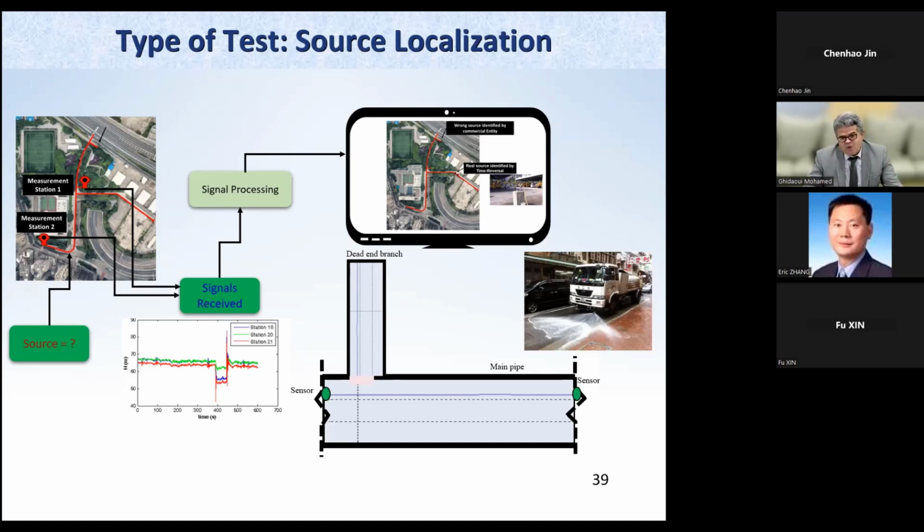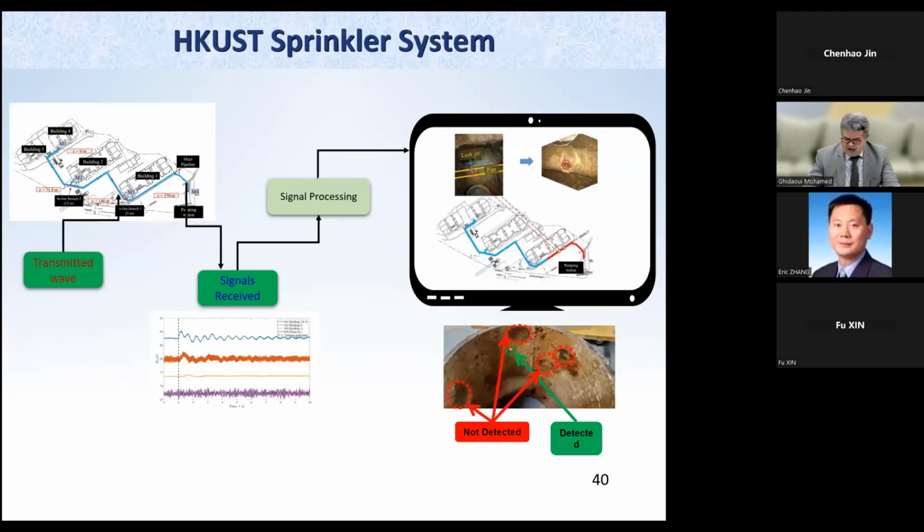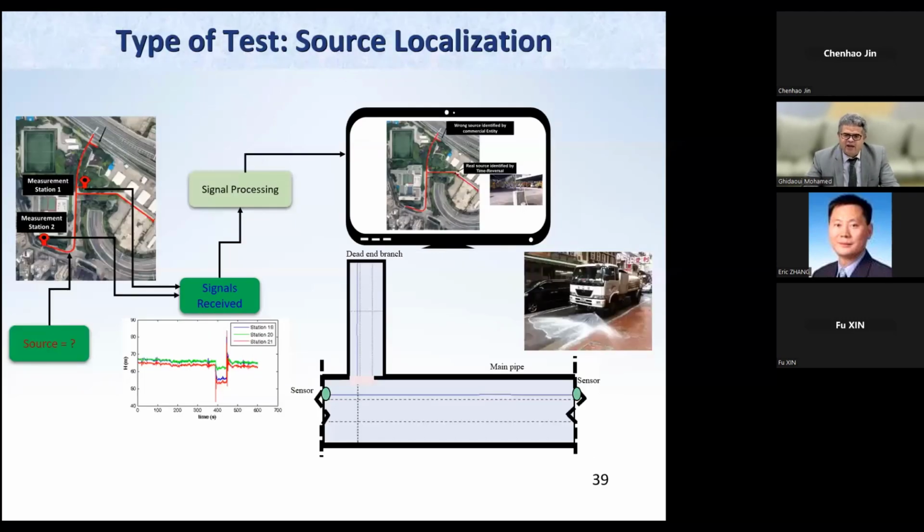And the question is why? So we took it and we used time reversal. This is where we had the measurement at the 2 green dots. We send it back, and this is on our model. We got a model of the system, and observe with me. The idea is where the waves meet, where they peak, is where the source is likely to be. So if our time reversal works really well, then the source should be at that location.